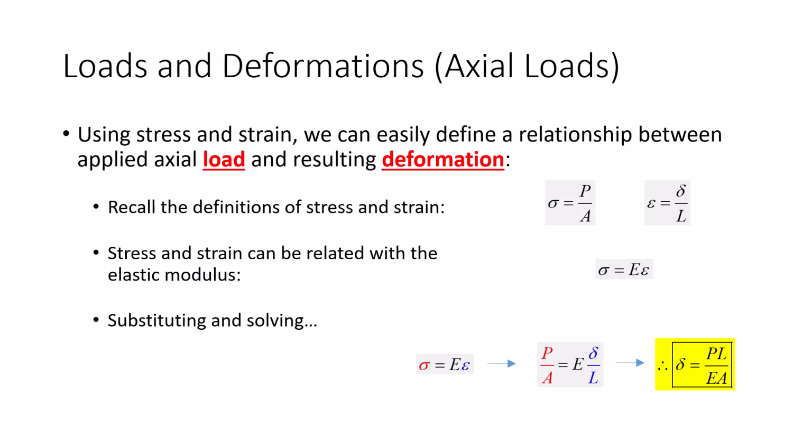Well, basically what you're doing is connecting the three concepts. If I apply the load, I can compute the stress. If I know the material properties of the pencil, I can compute the strain. And if I know how long the pencil is, I can take that strain and compute a displacement, right? Well, what we can also do is relate all of that in one big equation. So that's what we're going to do. Let's break it down a little bit.